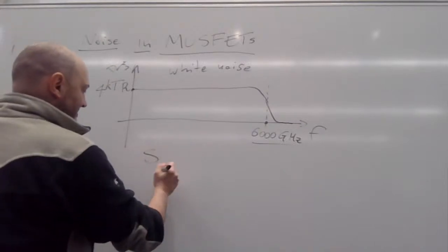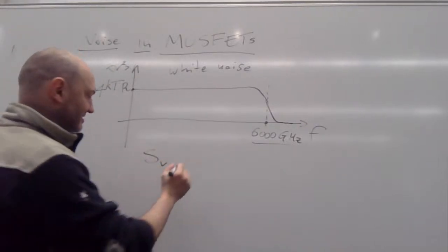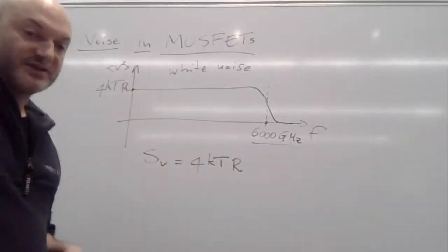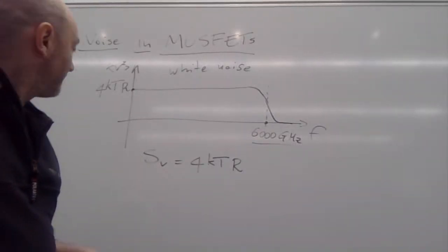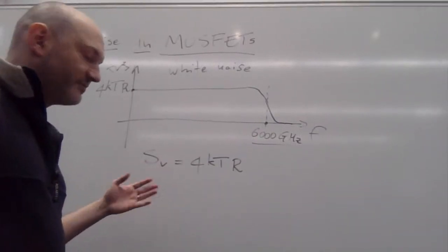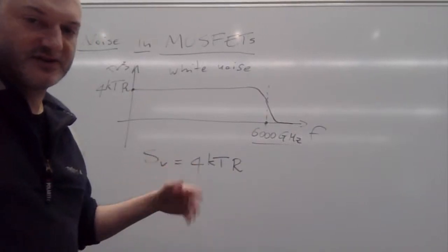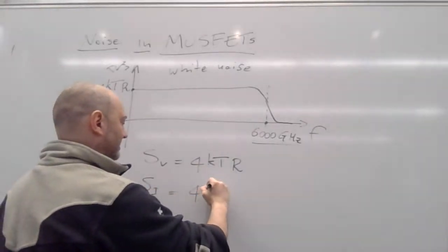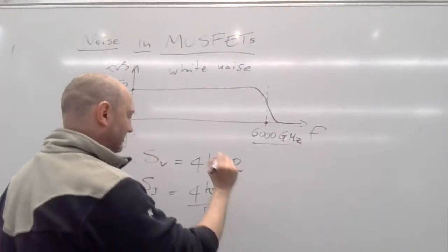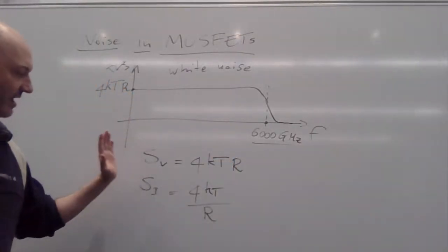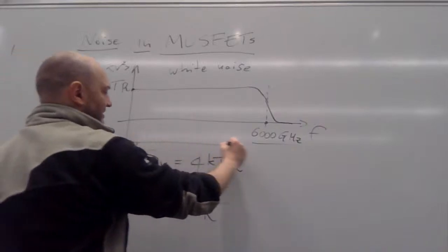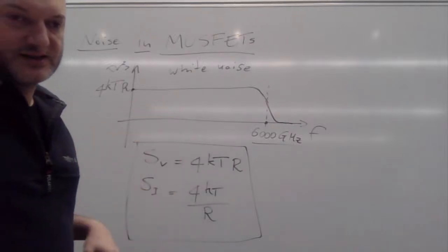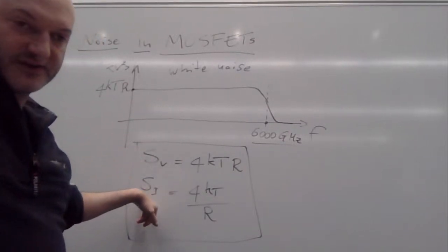So we got the power spectral density of the voltage noise is 4kTR, and of course we can consider the current spectral density, okay, by converting voltage to current using a Thevenin to Norton equivalent as usual. So this one is I with 4kT over R. Okay. So these two expressions here give us the white noise approximation of the noise spectra for voltage and for current.